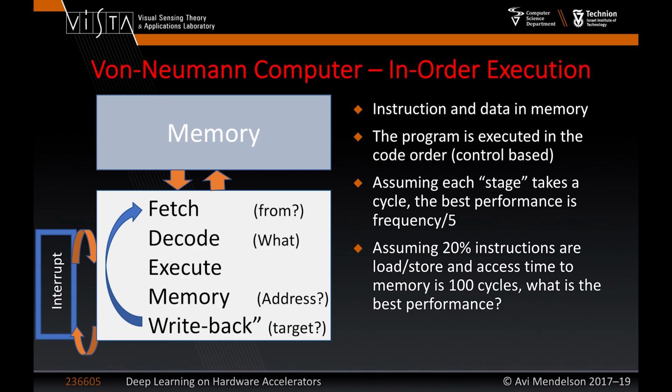Since they want to save power, which is very important for them, they prefer to do things with a slower frequency, spending less power, and to get a high bandwidth. So they trade very wide accesses with a lot of memory ports to the memory, but at a slower pace. So this is their trade-off.